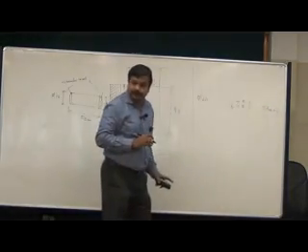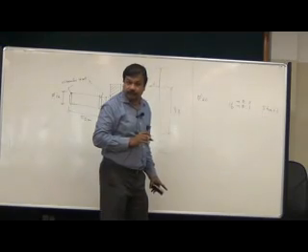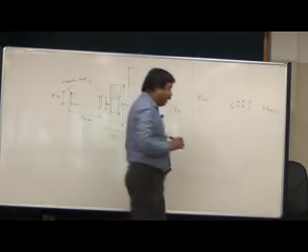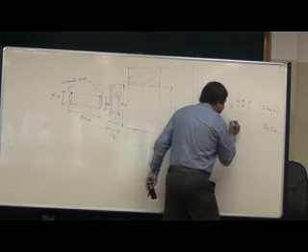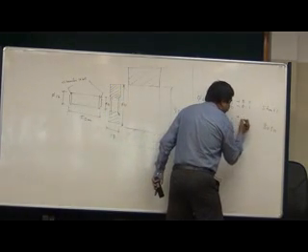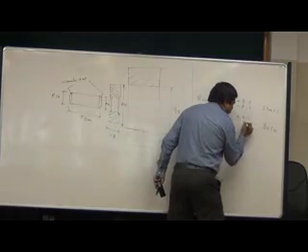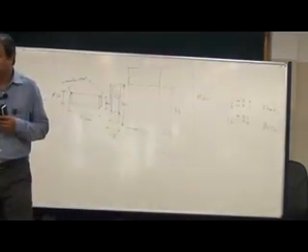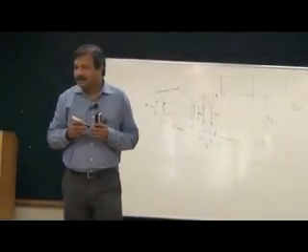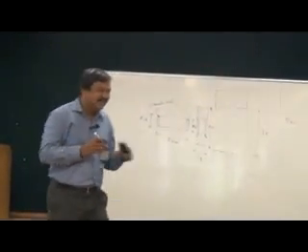This is the dimension. Now, for the bush, the 16 mm, I just make it plus 0.1 minus 0. Now let us analyze the situation.